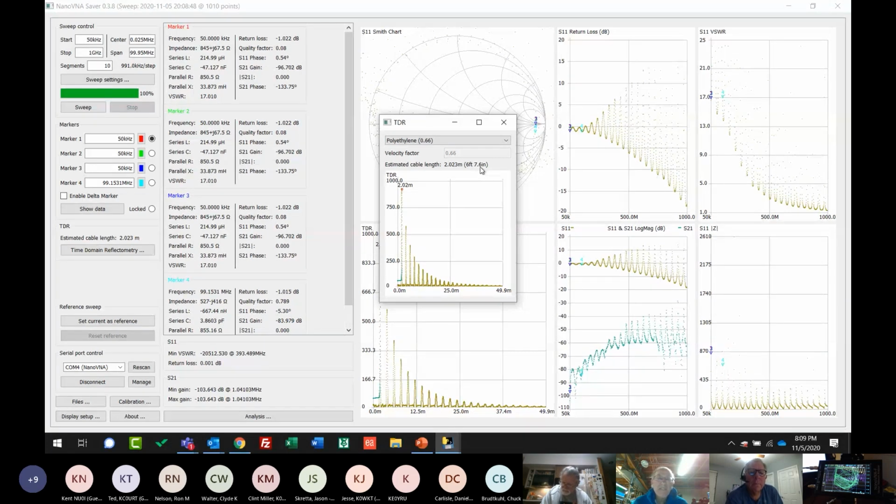inch. So when we look at this number, it's pretty phenomenal that just by bouncing some signals down a feed line, measuring the open end that's actually a cut piece of coax, it can tell us within an inch the length of what we've got. This could be used in the case that you've got a damaged piece of coax, maybe feeding an antenna, and you're having trouble getting a match and you're not sure where you need to go look.